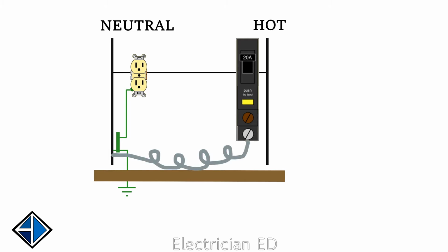They either have a pigtail like this, or if it's a plug-on neutral breaker, it will just snap right into a special panel designed for it. And you don't have to worry about connecting this. But if you have a curlicue white wire coming off of your breaker, it needs to attach to the neutral bar in the panel.